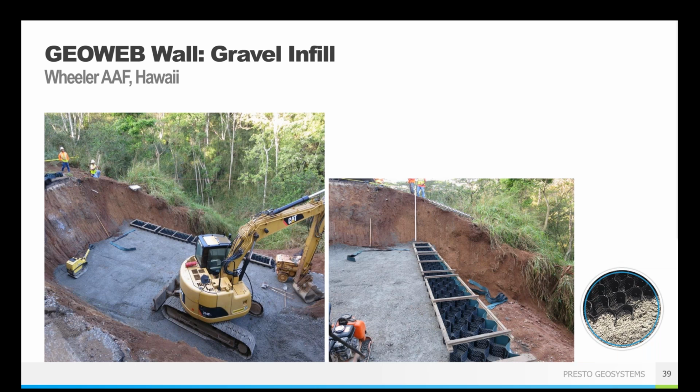And that way you don't have to worry about it clogging over time or potentially having that pore pressure buildup. But including other drainage, such as wall drainage, is a really beneficial thing to do as well. Let's see. So as you can see here, all of those panels are being stacked on top of each other.